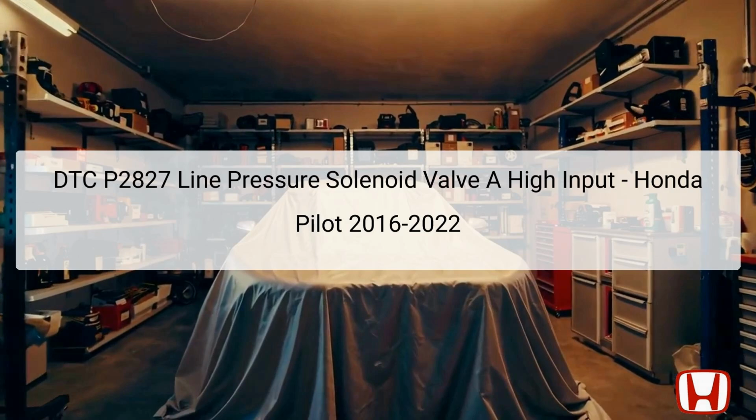In this presentation, we will explore DTC P2827, which indicates a high input from the line pressure solenoid valve A in the Honda Pilot models from 2016 to 2022. This diagnostic trouble code, DTC, suggests that there is an electrical circuit issue rather than a mechanical one within the transmission system. The line pressure solenoid valve A plays a crucial role in controlling the hydraulic pressure needed for shifting gears properly in automatic transmissions.